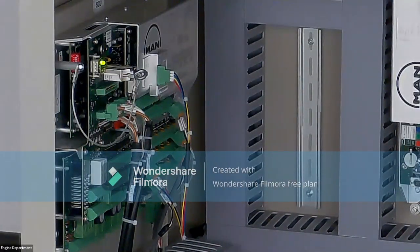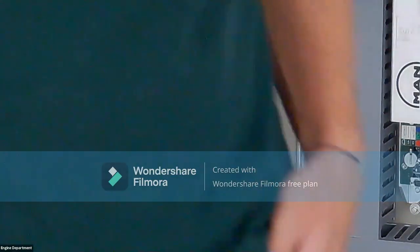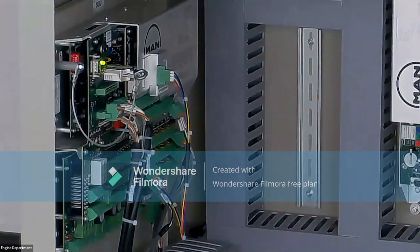Because the owners are looking to reduce the price of the engine, nowadays MAN is providing just one power supply, in order to reduce the price of the engine control system. Nowadays, you can find the setup of the engine control system with just 1 power source and a backup battery for 30 minutes of additional power supply in case of power loss.